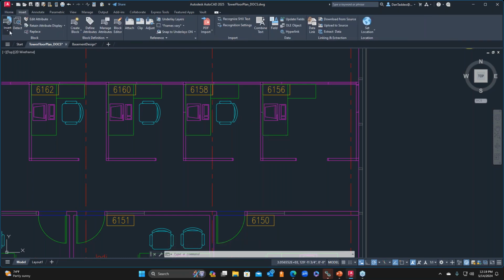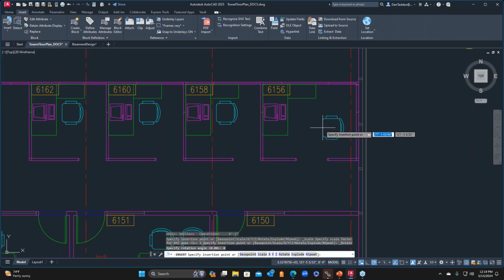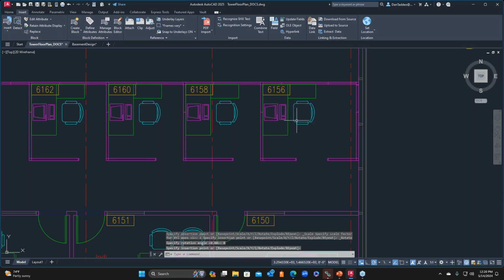But if you go into the insert tab and start inserting that same chair block, you can get close to the line geometry or the position. And if you take a look, it has that predetermined offset that's already there. And as I get into a closer position of the offset between the other horizontal line, you can see both the vertical and horizontal line of the depth is now illuminated with gold. This is the smart block capability.